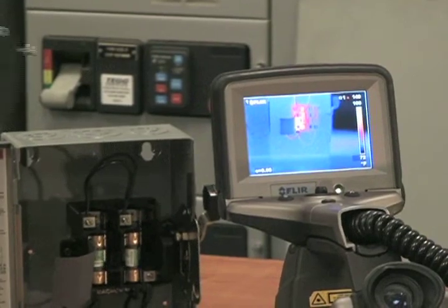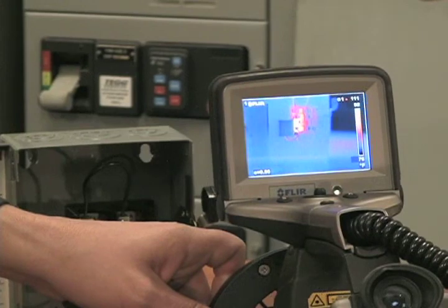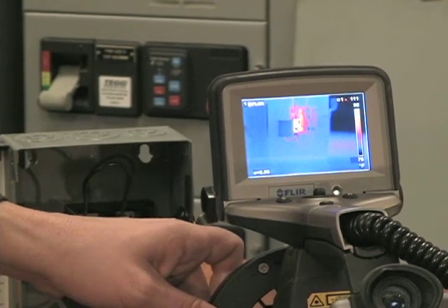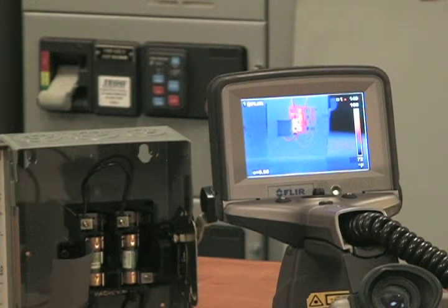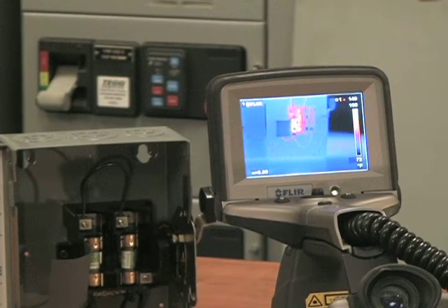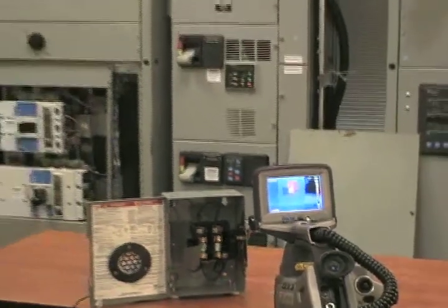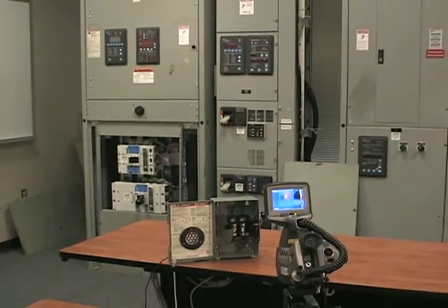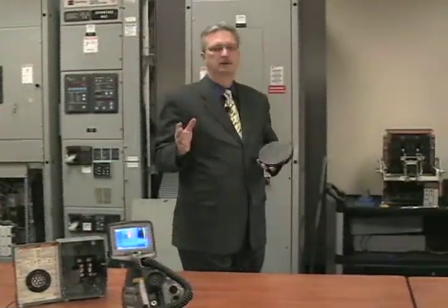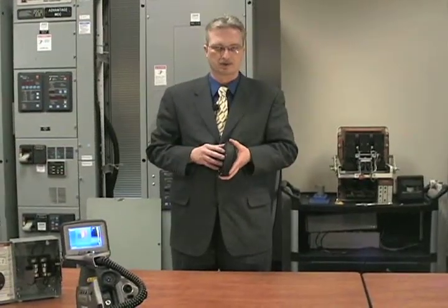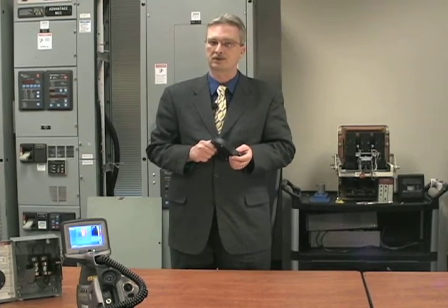If we place an infrared window in the path, we can still see clearly, but our temperatures have dropped significantly down to about 111 degrees. In actuality, the temperature is right around 149, but through the infrared window, we're having an inaccuracy because of the transmission loss. So an infrared camera operator has to set up the camera to properly measure the temperature through the infrared window, or else your temperatures and your temperature comparisons are wrong.